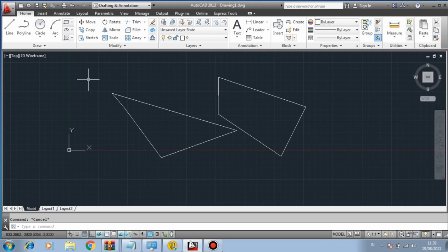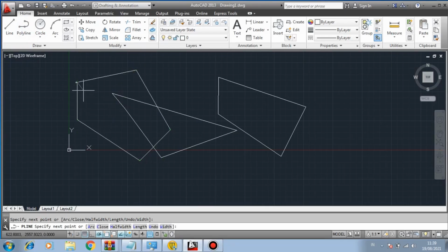was performed. For instance, let's say I want to draw a continuous line using the polyline tool. I would left click to define points, then finish the sequence, close the shape, and finally press escape to complete the command. Immediately after that, I can simply press the spacebar to repeat the process again. Now, it will immediately go back to the last command, which is line again.